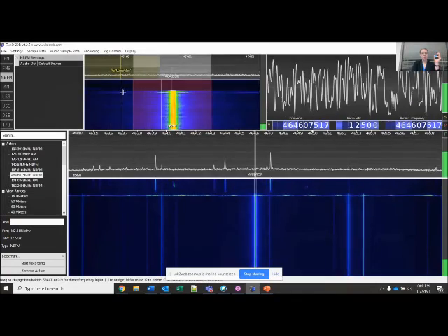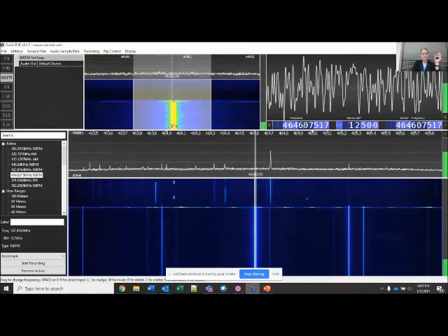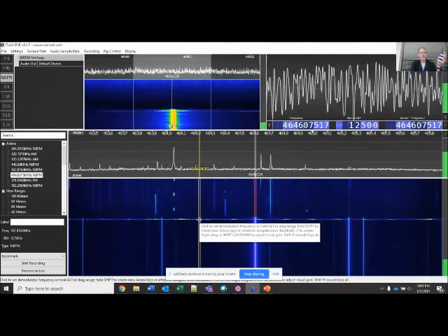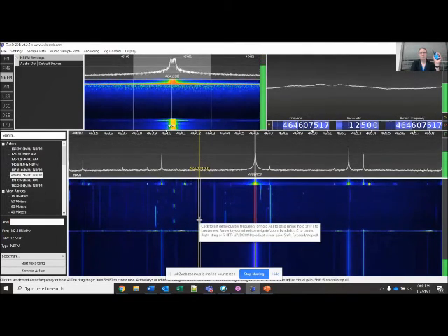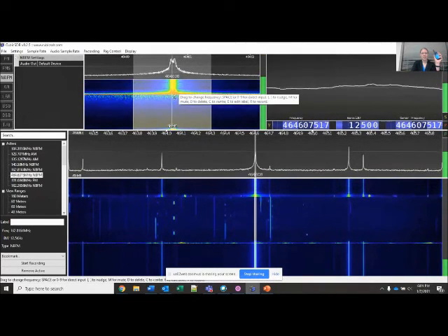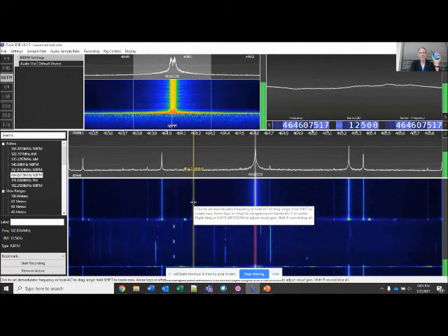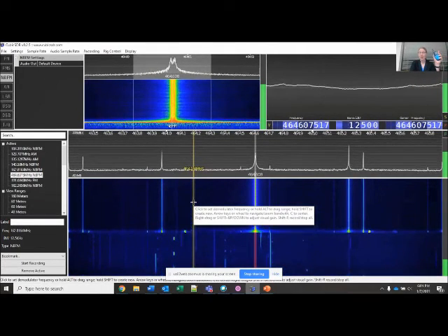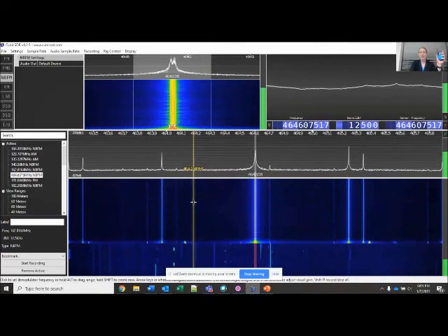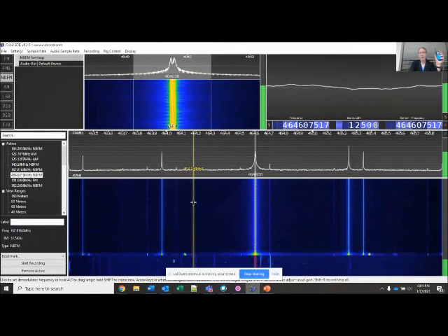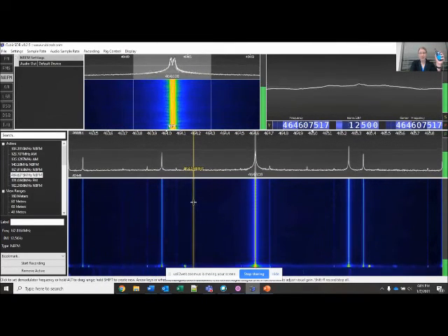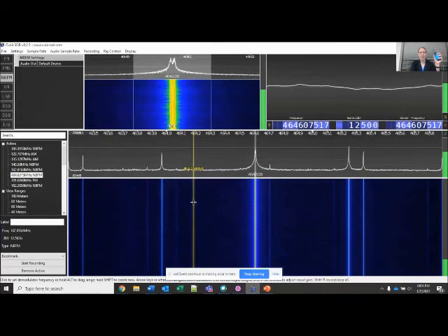It sends this kind of burst of energy across the spectrum. And when I turn it back on again, look at that pulse that it sends out when it turns on. It's really pretty amazing to see that the turn-on and turn-off transients all of a sudden spread its power along quite a wide bandwidth. Whereas once it gets to its steady state carrier signal, then it settles down a lot more nicely.